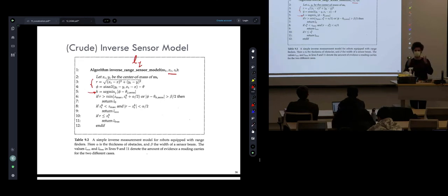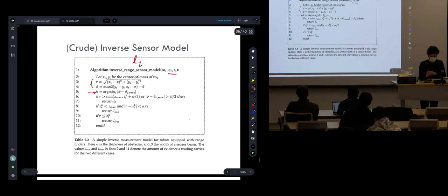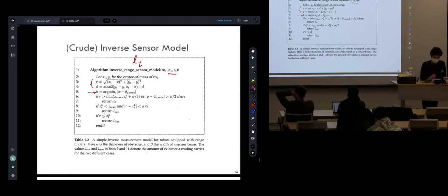Right? Because if the map cell in the sensor frame is located at, let's say, 30 degrees this side, and I have beams at like 25, 15, 0, 15, 25, then the closest one is the one that is at 25. There is no beam at 30 degrees. So we need to find a beam that is available on the sensor. Okay? So that's the closest beam. Now we work with the range. If the range R, nice change to R. This is the same thing as D.